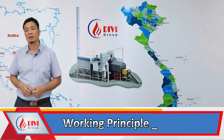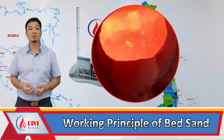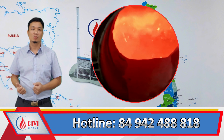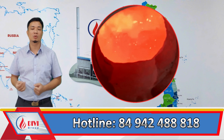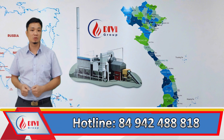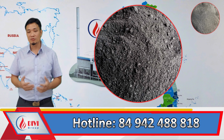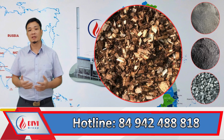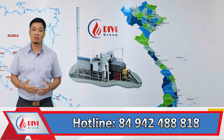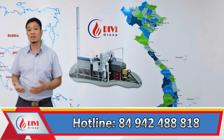Essentially, the fluidized bed material forms a fireball inside the combustion chamber. When fuel is introduced into this chamber and encounters this fireball, it ignites much more quickly. Therefore, it makes the fuel ignite far more easily. This is especially helpful for fuels that are difficult to ignite, such as Vietnamese coal dust, peat, anthracite, or fuels with high moisture content. This fireball helps maintain a stable combustion temperature in the furnace when using fuels with low calorific value and long ignition time.